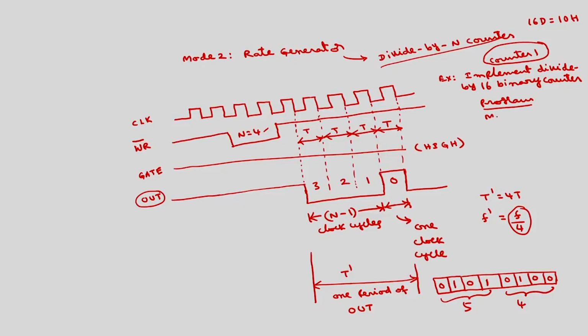So you have to load 54H onto the control register whose address is 03H, out 03H, AL. So these two instructions will load the control word register with 54H, so that counter 1 will be operated in mode 2 and it will act as only an 8 bit counter.